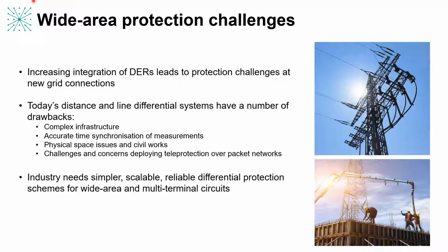So generally, there's a number of drawbacks which apply to both distance and line differential systems. As I've said, for instance, the infrastructure to support them can be very complex, requiring multiple powered units all talking to one another over packet networks. Because there's variable latency in these packet networks, accurate time synchronization can be quite challenging. And also, there are particular concerns about deploying teleprotection over these networks, thanks to that variable latency. And from a purely practical perspective, if you want to install new measurement schemes, there's implications around physical space, weight, and the requirements for civil works at the installation location.